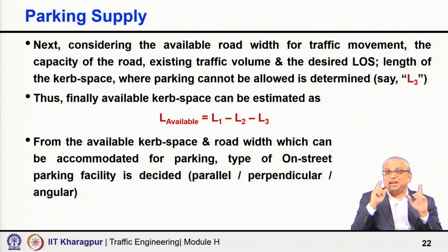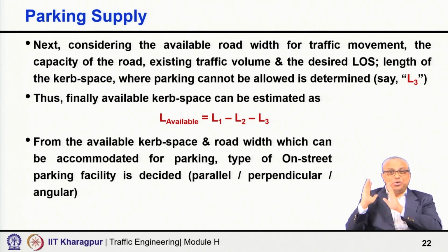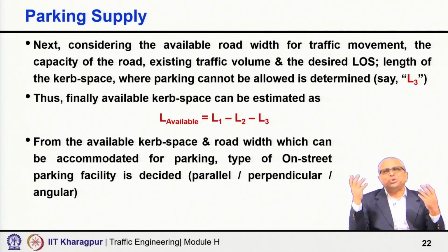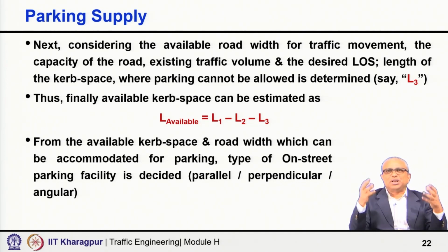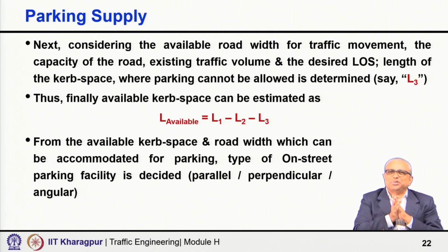So, it has to be all decided judiciously, looking at the existing traffic volume, the width of the carriageway and shoulder altogether, and what kind of parking arrangement will be acceptable, so that it will not have a serious detrimental effect on the moving traffic stream, and also look at the demand. Sometimes the alternative is not available. What will you do? You have to accommodate a little bit. Maybe as and when you improve public transport and other alternative facilities, then you slowly tune it up, reduce the angle and make less parking space available. Then the social acceptability of whatever you are trying to do.